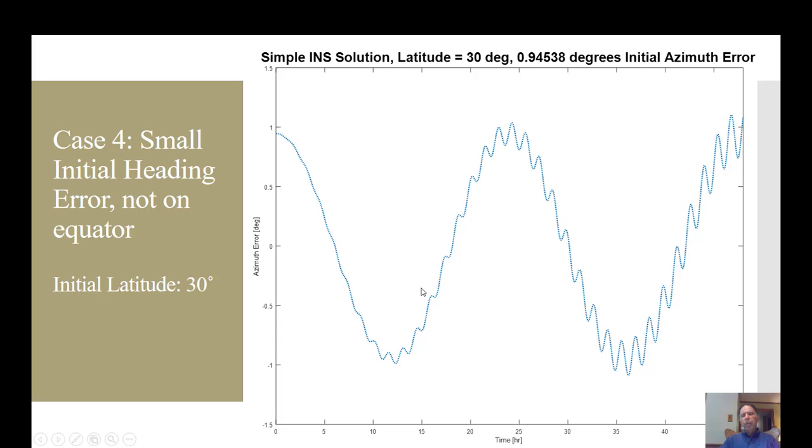I'll also point out that as far as Schuler oscillations, most of the time we operate for long-term inertial navigation, and that generally means more than a few hours. We operate in a damped configuration, meaning that we utilize an external velocity aid, such as an electromagnetic log or Doppler velocity log to aid the inertial navigator, which helps the inertial navigator minimize Schuler oscillations and keep them bounded.